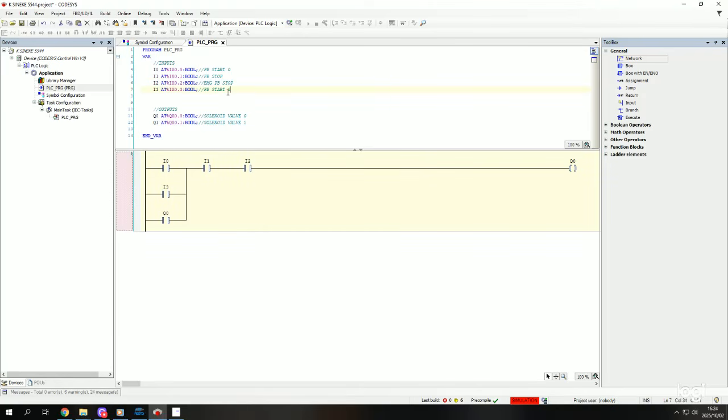Okay, so we are building on the previous exercises. We introduced a proximity sensor that was sensing the rear end position. So now we are inserting a proximity sensor which needs to retract automatically the piston rod to its rear end position. So our I3 becomes our sensor.